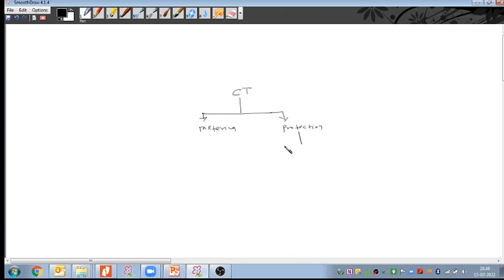And this protection we again divide into two parts that we mostly use. One is the P class protection CT, and next is the PS class or PX class protection CT. So when we talk about CT sizing, we have to do this core sizing calculation. The metering core selection parameters and sizing calculations we have discussed, and the protection class core selection parameters and sizing also we have discussed.